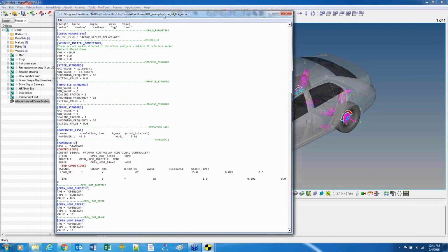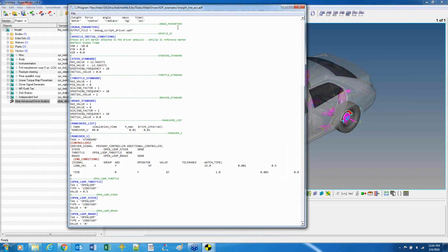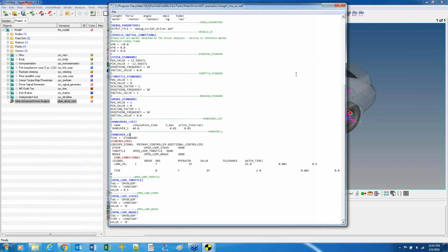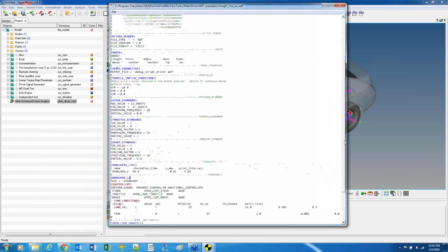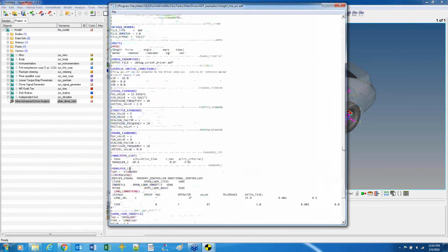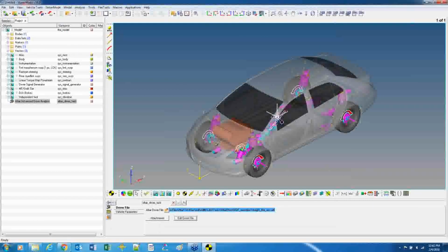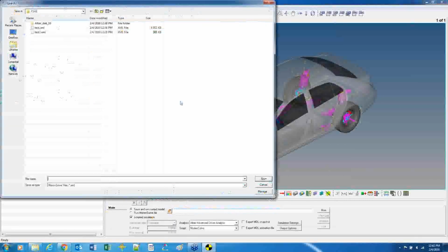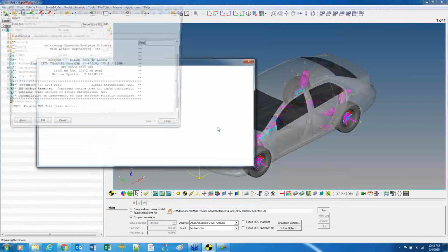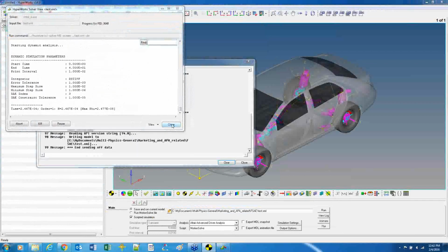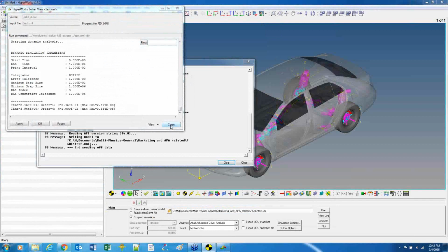And the key thing that comes with that is it implicitly takes into account the state of the vehicle when you transition from one maneuver to another. That's really one of the big gains from this approach versus having to manually capture where the vehicle state is and then continue on. So this is done by just adding that type of advanced driver analysis, and then the main work you do is go in and edit the pretty small and easy to understand file, and then it will run from there. This one starts out a little bit boring, at a straight line drive. We can go ahead and run that and get a look at how this driver is integrating with the overall system model. This just takes half a minute to run as well.